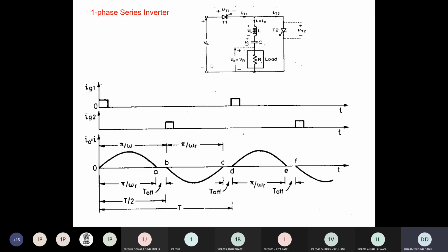Clear? So suppose a short circuit happens here on the supply side. Suppose resonance happens. In the resonance condition, what will happen? Xc is equal to XL. So in that case the impedance of this part becomes low, and a very high amount of current flows from the supply. When T1 is conducting, if resonance happens, that can damage your thyristor. Clear? So in that condition, to avoid damage to the thyristor, you can put in inductors, of very high value. Clear? So there are two functions of inductor: one is to act as a filter, and another is to limit the source current.